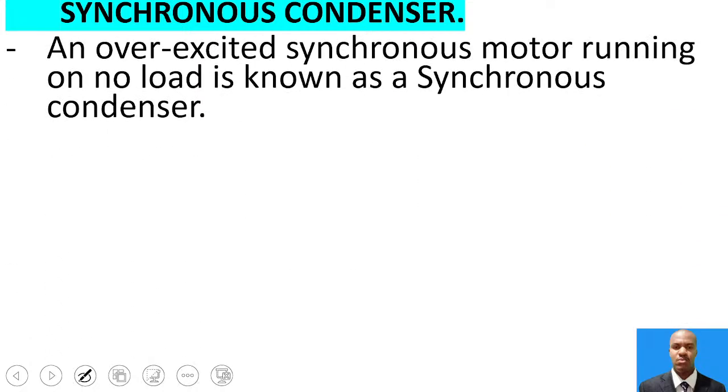This motor is simply connected to your three-phase supply, and what it does is it takes leading current, and this makes it behave like a capacitor when connected across a supply.